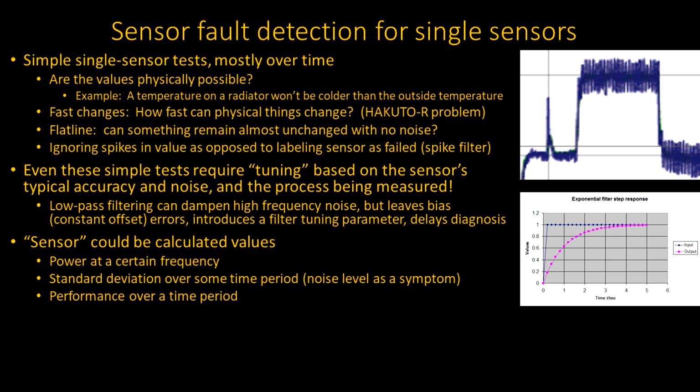And when you start getting that, the measurements themselves get very noisy, and that also has a bad effect on the downstream pump or compressor. It causes it to vibrate quite a bit. So sometimes having a high level of noise is in fact a symptom, and you'll take that as a form of measurement. Not the sensor value itself, but just the fact that it looks like it's being noisy, maybe reflecting something that changed in the process.